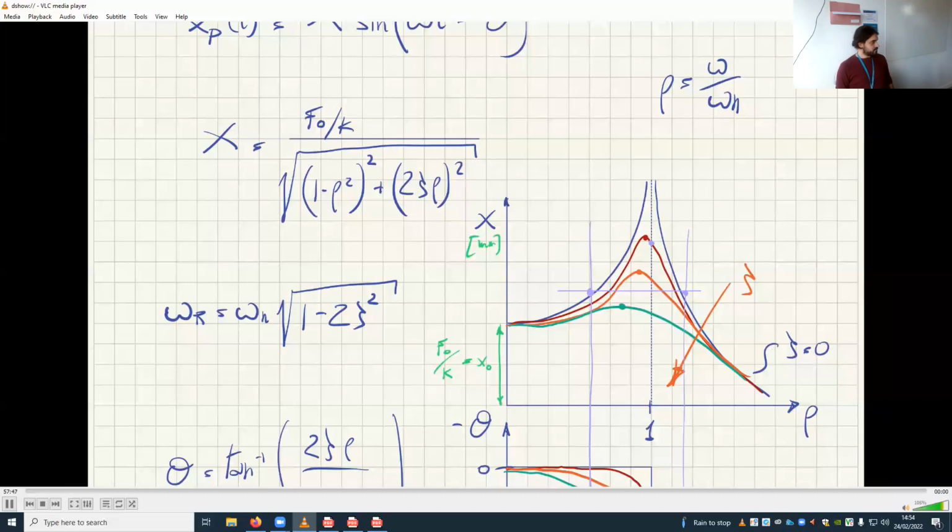Yes. Can you just change omega r for omega n? What do you mean you can change omega r for omega n? If it says find, yeah, you just place omega, but this rho is omega r over omega n. That's it. So rho is always omega over omega n. If you are forcing at resonance, that is omega r over omega n. If you are forcing at the natural frequency, that's omega n over omega n. That's one. Exactly. You just change the numerator omega to omega r. That's it, because that's the only thing that changes with the external agent.